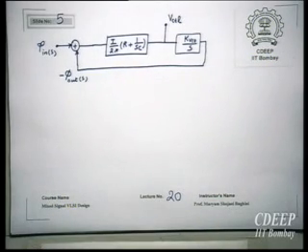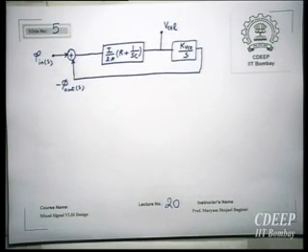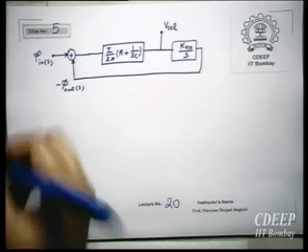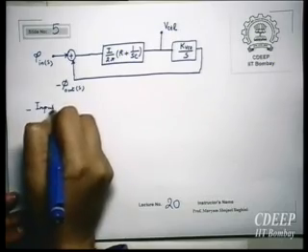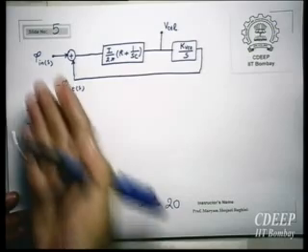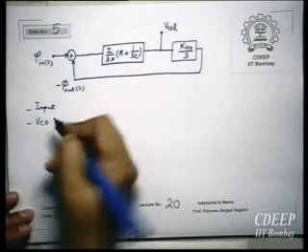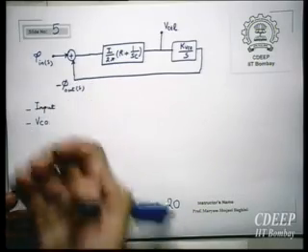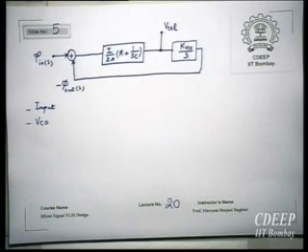Okay, so this is a simple model of a charge pump based PLL. There are two sources of jitter. One is jitter coming from the input, which may or may not be present, depending on the accuracy of the input. The second one is jitter coming from the VCO. So how will these two affect operation?